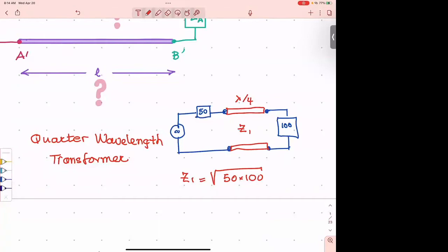All right. So to have the maximum power from the source going into the transmission line, what do we need? We need to have an input impedance there to be 50 ohms. Do you remember that matching condition? You remember conjugate matching? We have it even for complex internal impedances.